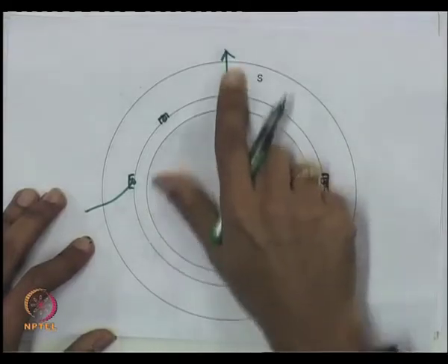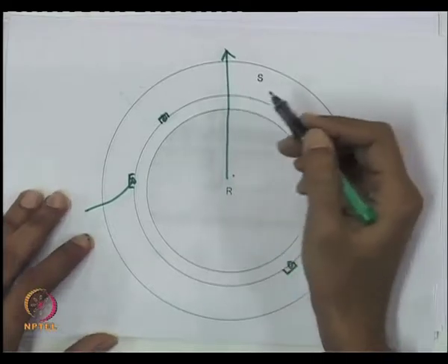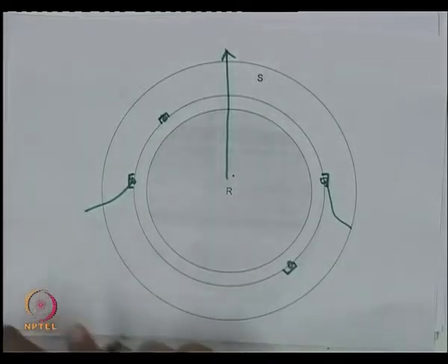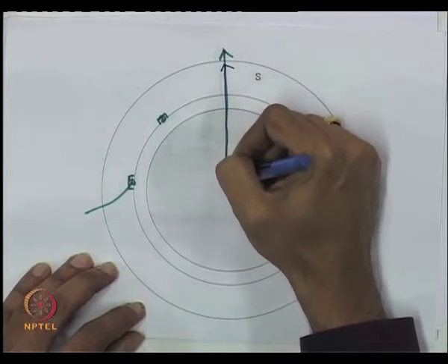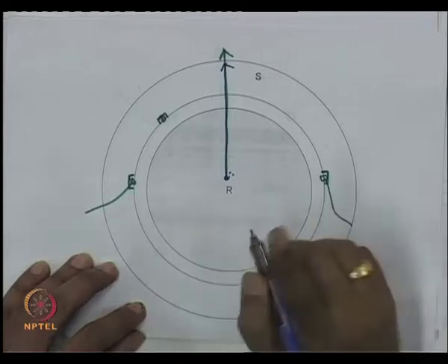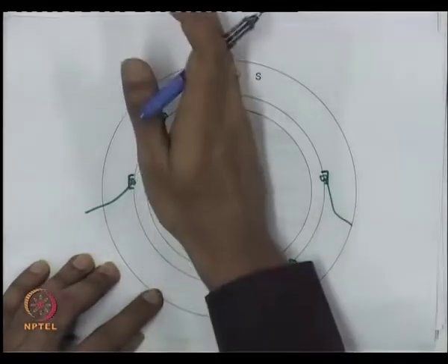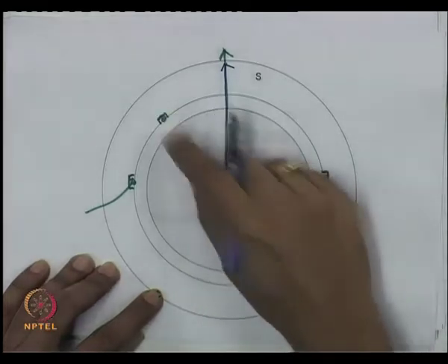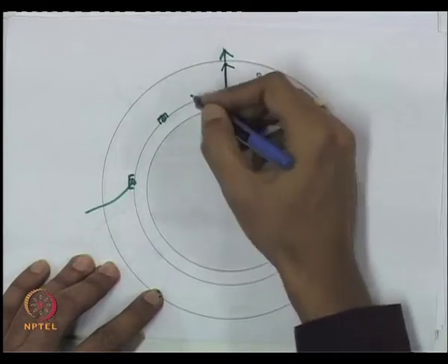It means that the maximum is in this direction and it drops off sinusoidally, and the flux also, since the reluctance is the same all throughout the air gap in a cylindrical pole machine, can be represented by this vector. But as I mentioned in case of the mutual inductance between the A winding and the field winding, the flux flowing in this direction, the amount it links with the B winding is not the same. For example, we had discussed this before.